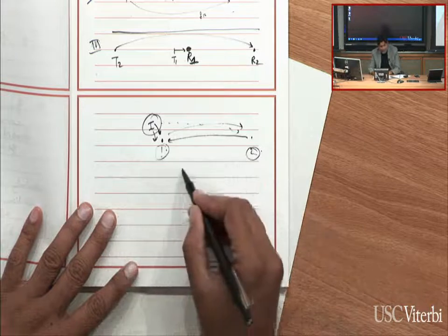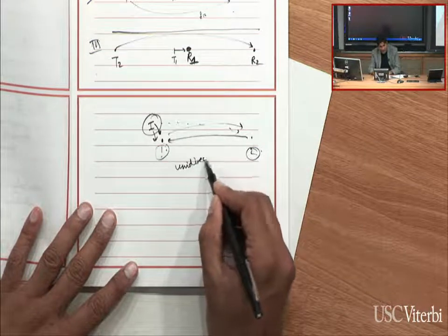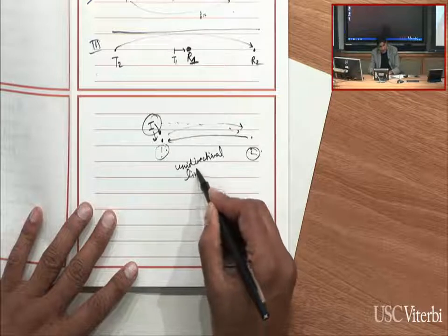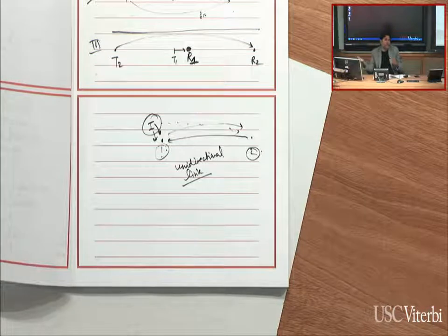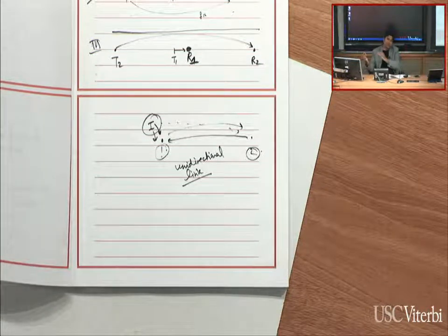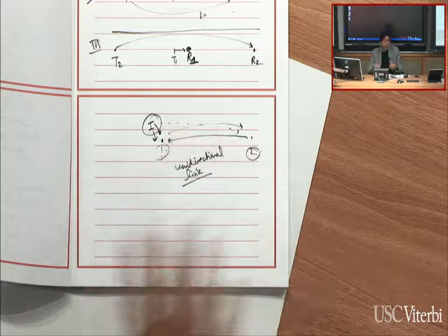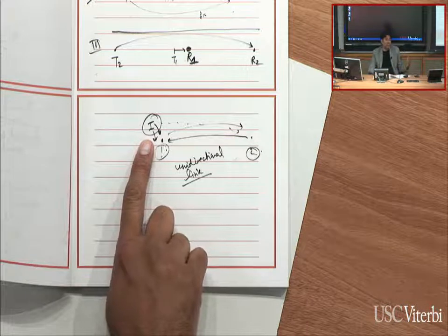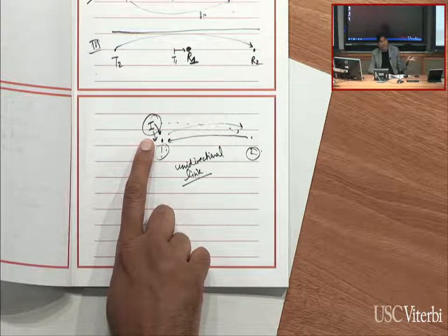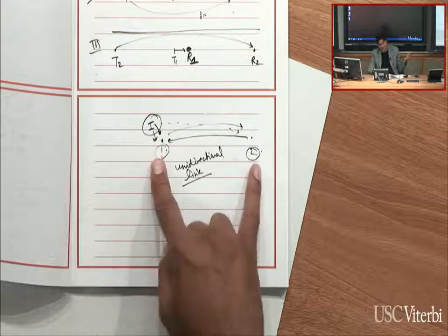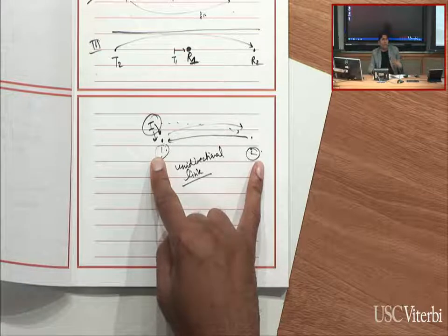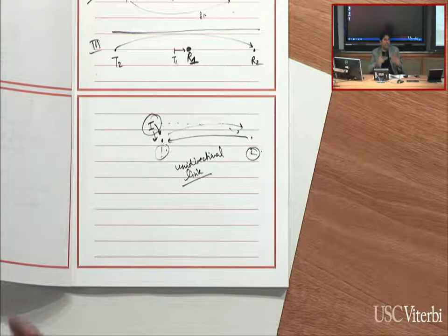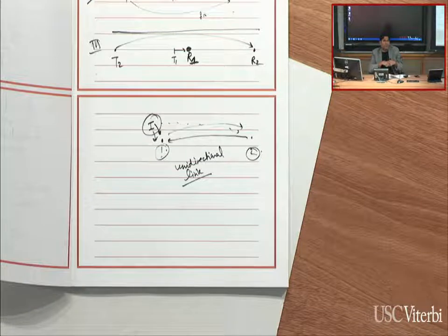And this is, in fact, an example of a unidirectional link. So when you have interference that you want to take into account, different receivers might be experiencing different amounts of interference. It can happen that one node can talk to the other, but not in the other direction. So sometimes when we're deploying these low-power sensors, these are issues that we worry about. The additional interference is not a shower, it's a Wi-Fi access point nearby that's blasting away. And so this node is unable to decode signals coming from a different node, but in the other direction, communication is perfectly fine. And if your protocol assumes that if you can hear someone, they can hear you, it's going to run into trouble.